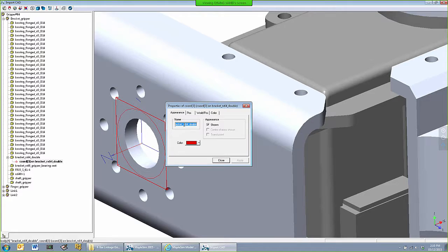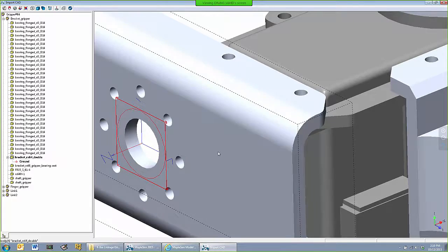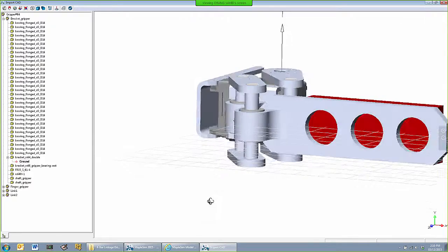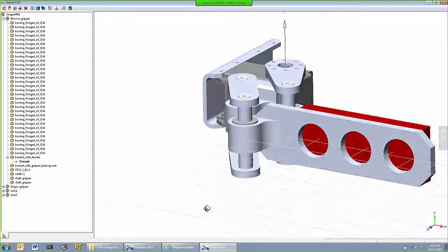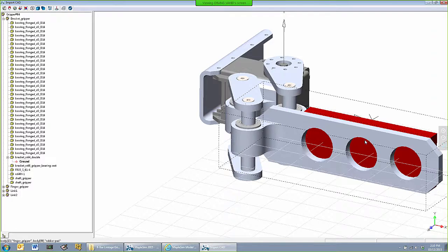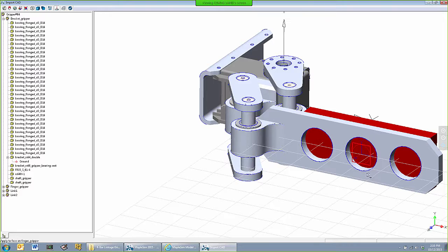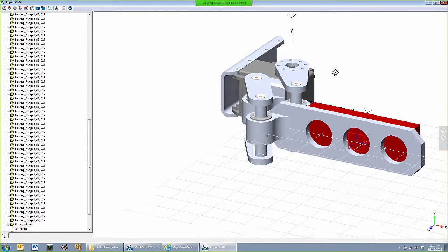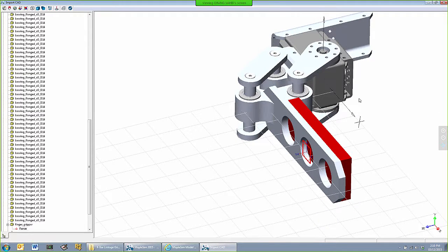I'm going to change the name to ground, so when I'm in MapleSim, I can use these names to quickly reference where the ports are and what port I need to connect different things to. Now I want to add an external force, let's say in the middle of the finger. So I'm going to add another to this circular hole in here, seems like a good place. And I also rename this to force. So I now have 2 coordinates added for my external connections to the system that I'm bringing in.